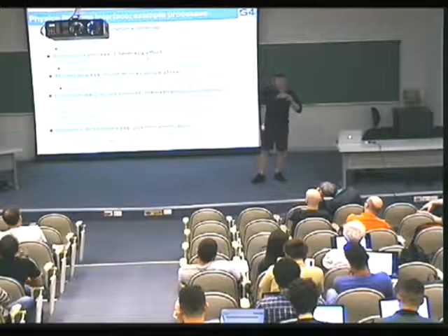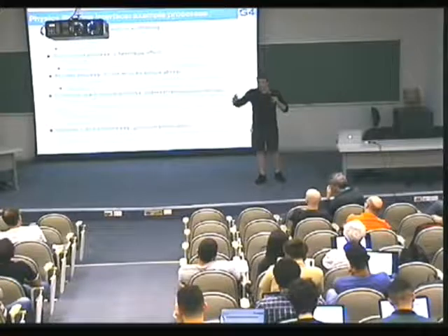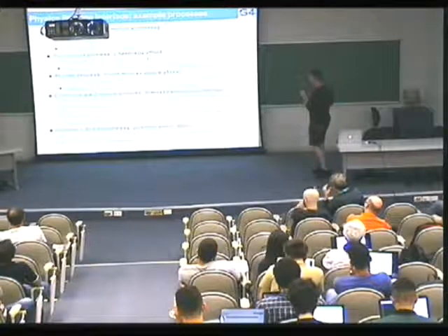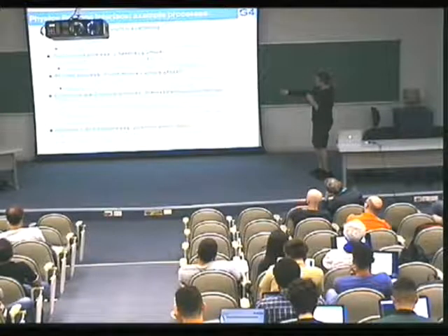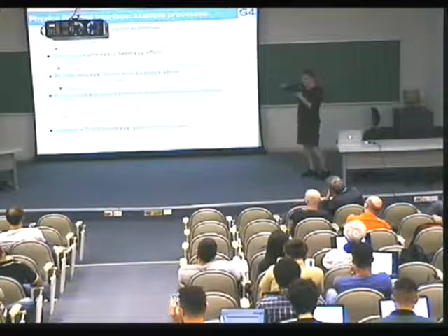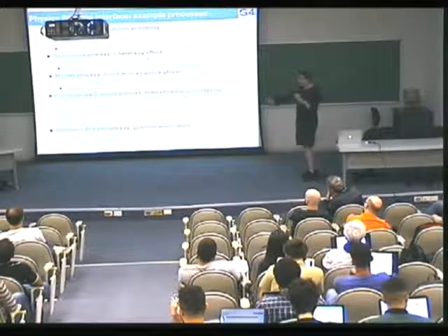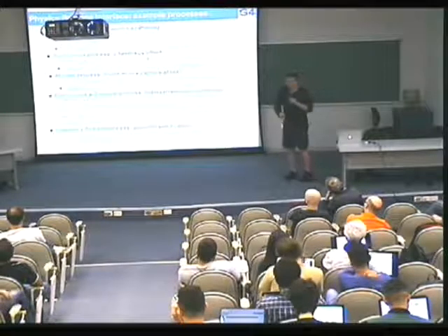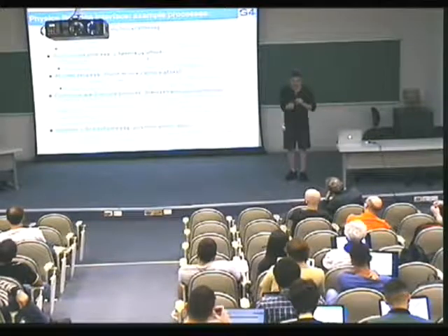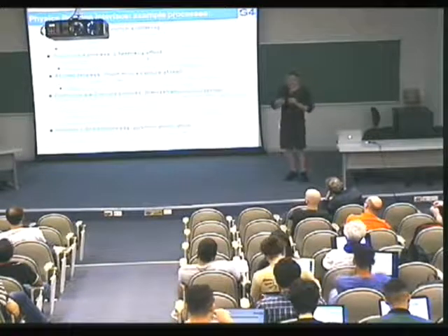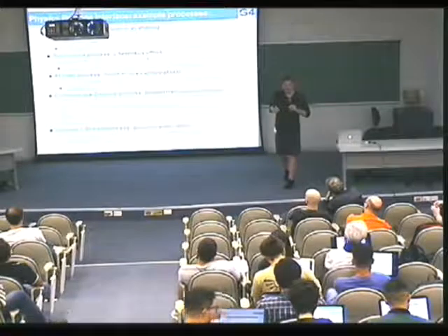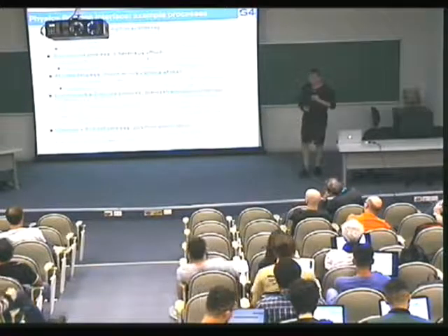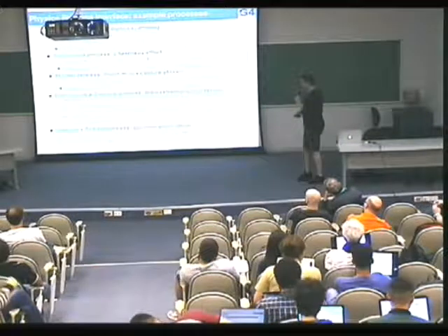So when the particle is moving from the pre to the post-step point, there are many photon emissions along the step. So for these kind of things that are happening along the step in a continuous way, what needs to be implemented in the along step get physical interaction length is how far you let the particle go, okay, and what's happening while the particle is moving, this photon emission, you need to implement in the along step do-it method.